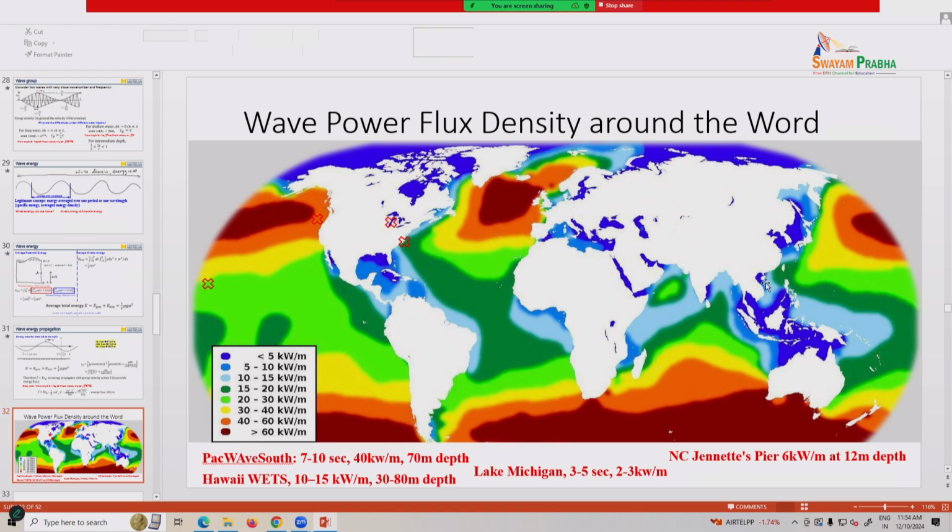The region is pretty small, it's 5 to 10 kilowatts per meter. And they built a 1 megawatt wave energy converter, and they tested it in the water. It has been there for more than half a year, and on average they produce more than 300 kilowatts. And there are two good things about the technology. One is the modular design, and each module is 60 kilowatts. They replicate different modules. Another thing is they have a very smart design for the wave capture structure. They call it Sharp Eagle. When we talk about PTO, I will mention that again.